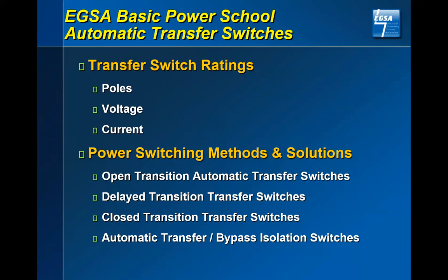When you're looking at the different methods, the most common one is what's called open transition. That is a term called break before make. It is either typically connected to your utility source or a standby generator of some type. However, when you're doing that switching, even if you're going back to the utility once it has returned, there will be that momentary blink of power as you open from the generator and you close to the utility.